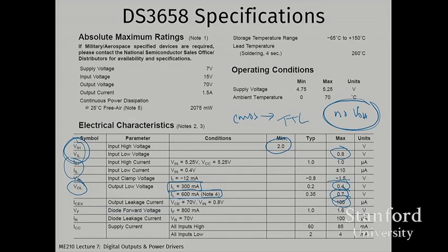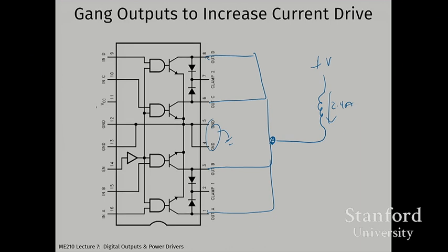These numbers for the voltages in the output low state are pretty good. But one thing you want to remember here is that you've got this current flowing that goes to these connections and into these output pins. If this voltage, this VOL, is 0.7, you've got power dissipation inside this chip, inside of the 3658, which is equal to VOL times IOL.